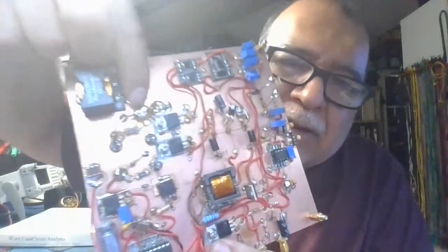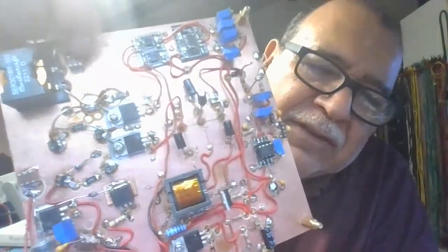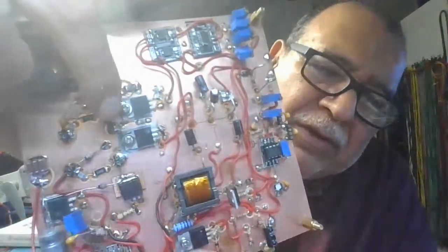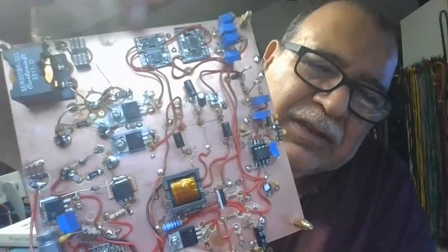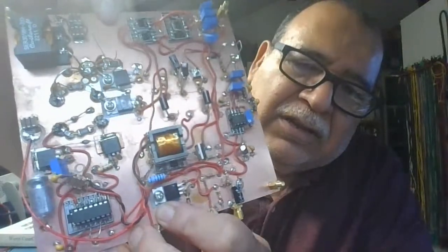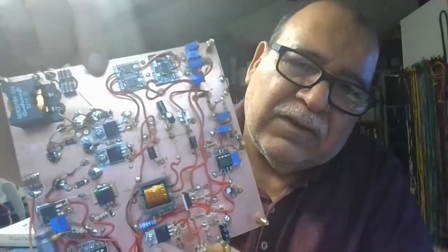See, so that's what most of these are. You might be able to see this one right here. That's a big cutout. See the cutouts? Right there, you can see two round ones. There's another two round ones. So that's how you can attach stuff. The nice thing about this is that it's a good ground plane. And if you put the wires close, then you should get much less noise.